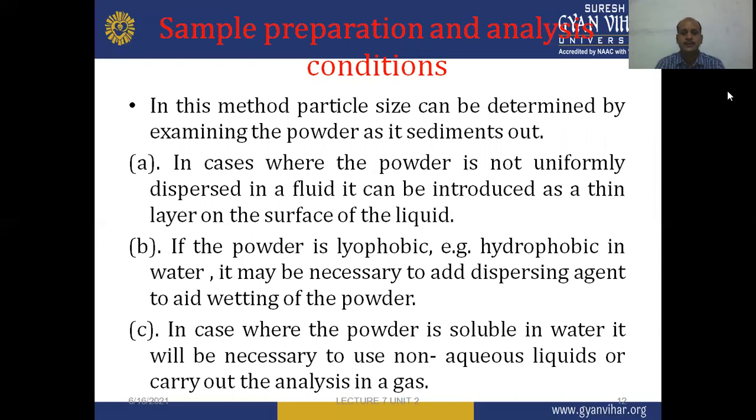In cases where the powder is soluble in water, it will be necessary to use non-aqueous liquids or carry out the analysis in a gas system. So these are the different sample preparation and analysis conditions for the sedimentation method of particle size determination.